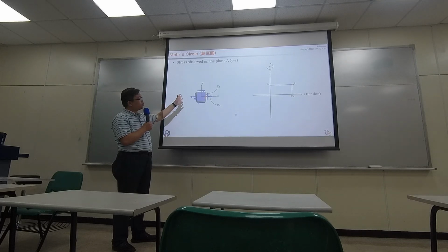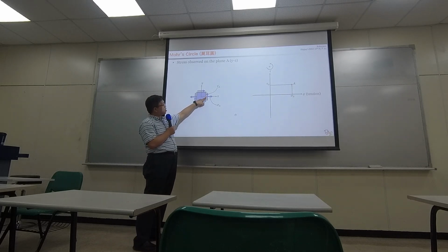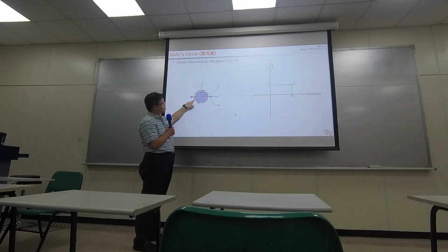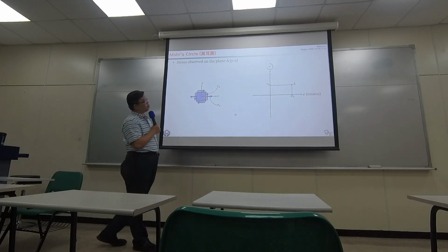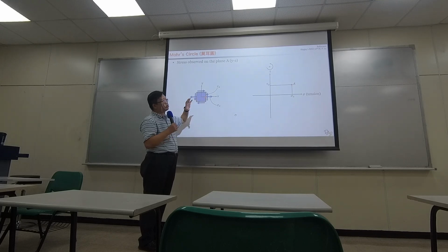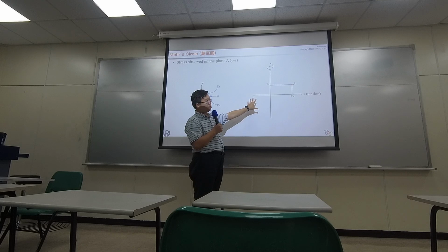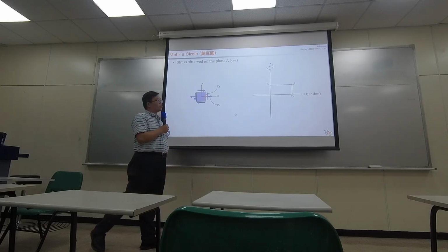If you forget about Mohr's circle, let me remind you. You are going to walk around the element, and you can start from any point. You can pick a point on the edge right here, for example the one on the right-hand side, let's say point A, and see what kind of load this position is carrying. Let's keep a record of the stresses applied on this point using the diagram on the right.